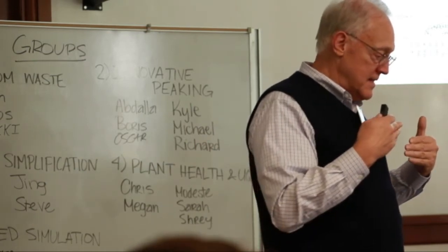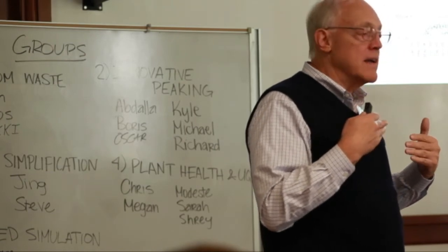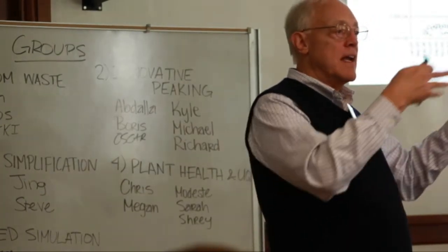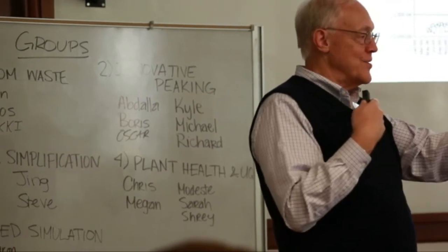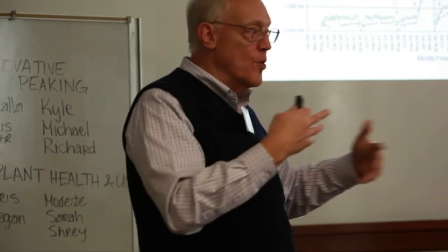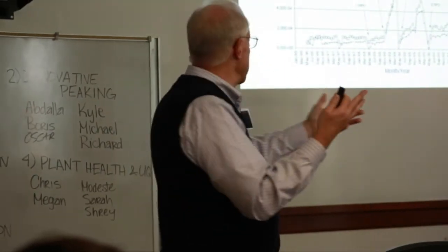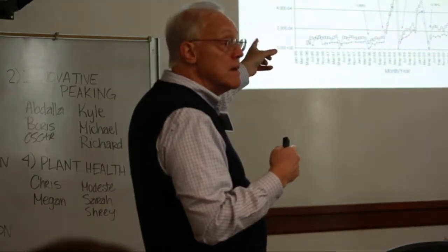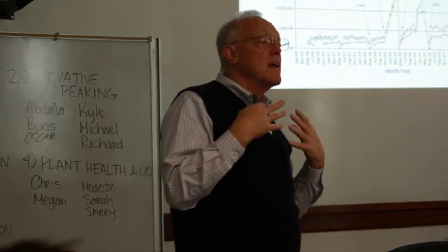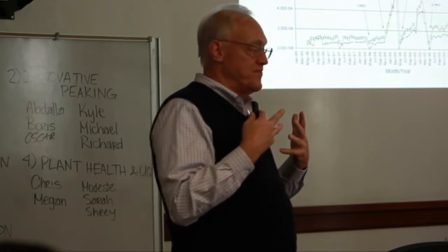In a reactor like Davis-Besse, with a dry containment, I sample the air condition all the time. That's the instrumentation need. Sample the air, make sure there isn't airborne activity beyond a certain amount, or trends in airborne activity beyond a certain amount, and that's what we're measuring here. It tells me that all's well on the inside of containment.